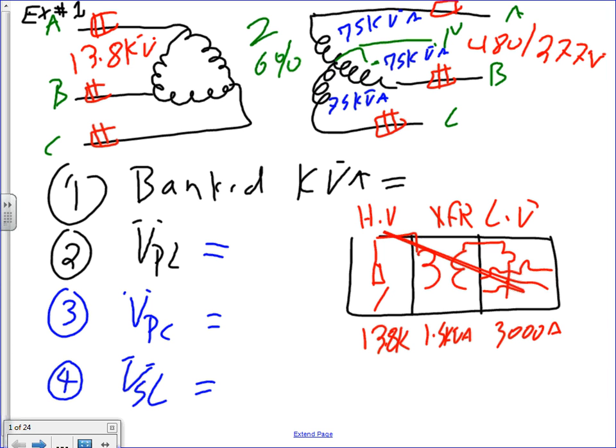Why would they do something like this? Clean cut, beautiful. So you go to Mayo Clinic, guys, Gonda building, the 13th floor. They take a feeder coming from the basement of the Mayo Clinic Gonda building and pull that medium voltage feeder right through the building, all the way to the 13th floor. That feeder will land into a unit substation like this, into a disconnect and fuse, feed a transformer, and this will be your 480 system.